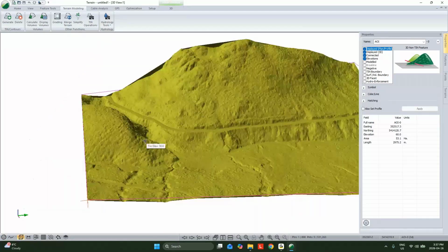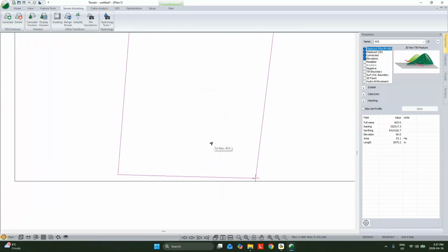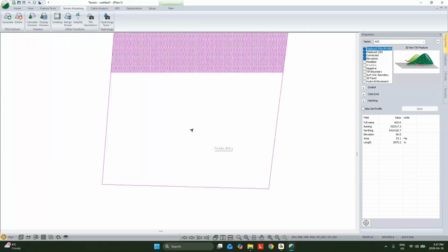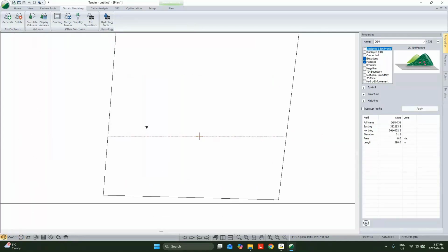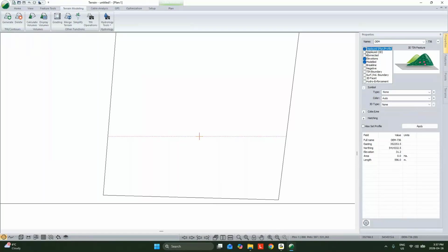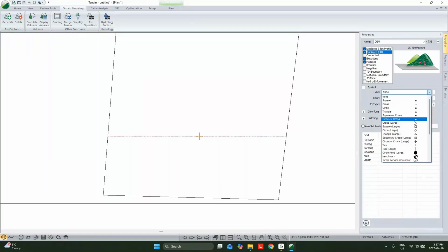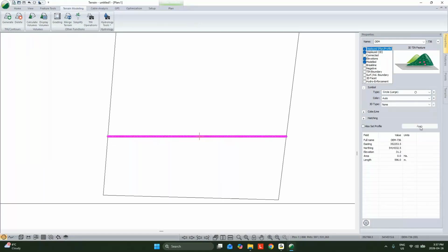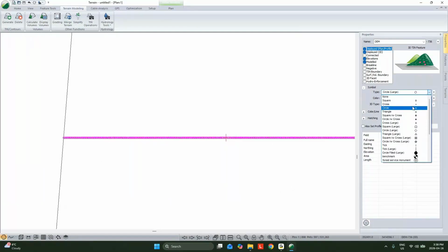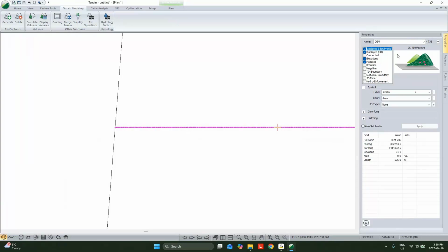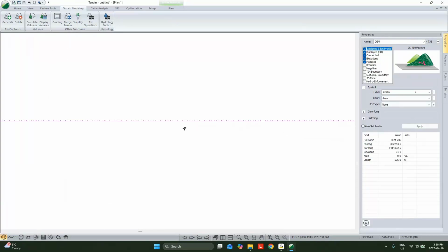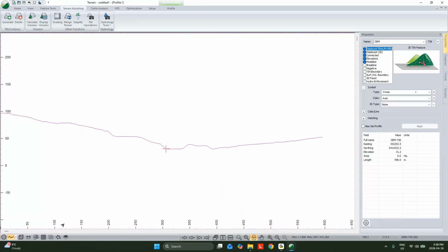Now this next one, the feature simplification tool, works well for DEM data and contour data. I'm going to grab one of these DEM features, and we're going to use it as a little bit of an example. First, I'm going to make this so we can see it, even when it's not selected. I'm going to make it so we can see each point. Actually, we'll use a different symbol, and we'll make it connected. And we'll look at our profile.